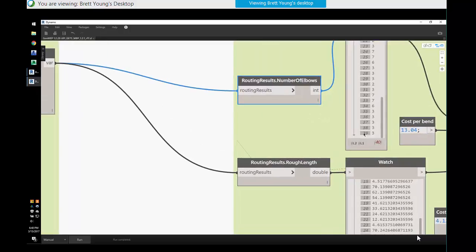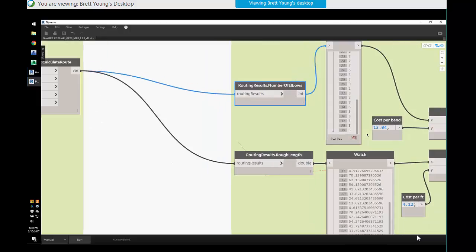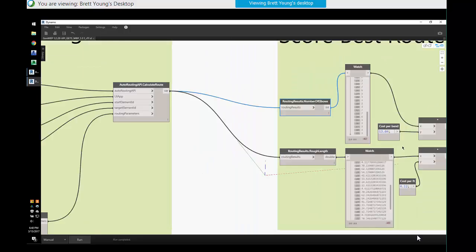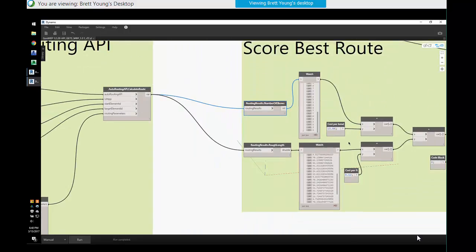And to kind of talk about that calculate route, what that means, we're calculating the route without modeling it within Revit. Because if you model it within Revit, you get a higher overhead and more lag. So we're doing a fit to make sure that we find a polyline, and then we draw the conduit on top of that polyline. Yeah. So if we don't have to draw it, we can just use that polyline as a distance. We know every time it turns.